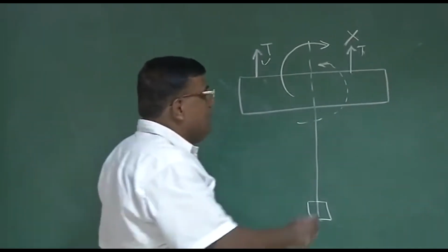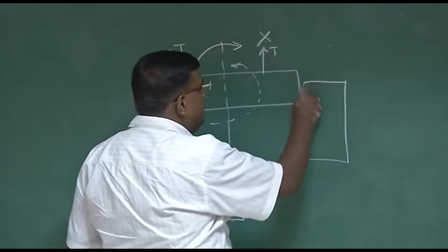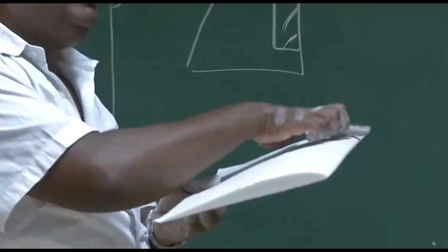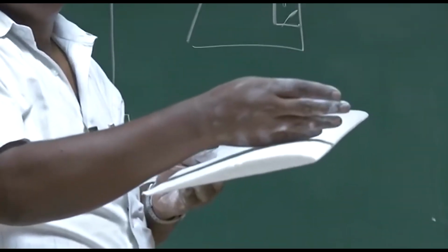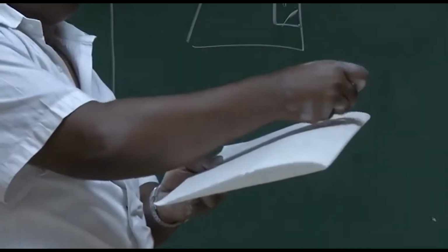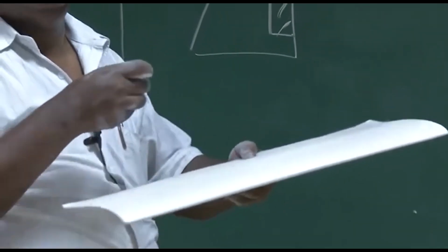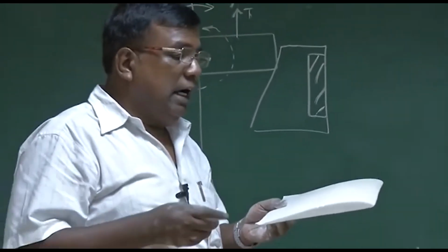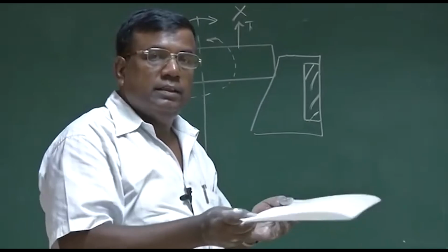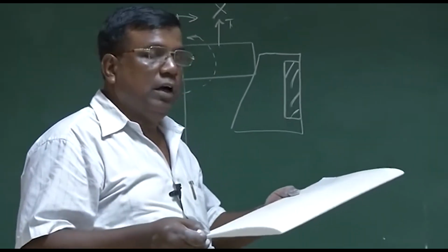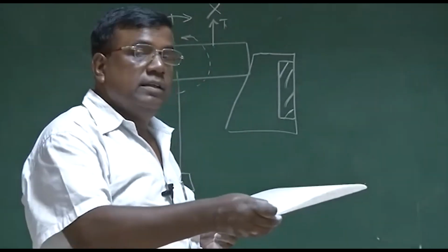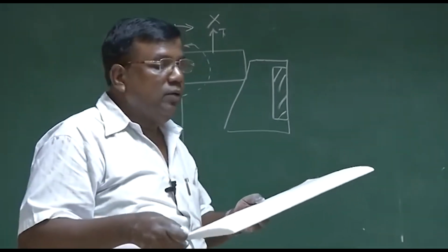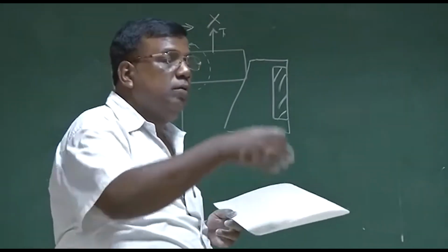Obviously, we have got the rudder, right? You know that? There are two engines, one here and one here. Let's say the right engine has failed. Because this thrust is operative, it will turn the airplane like this on the ground, which will be very dangerous. To ensure that it doesn't happen, I have to generate a moment in the opposite direction. From the top, because of this thrust, a clockwise moment is coming, so I have to generate an anti-clockwise moment when I look from the top.